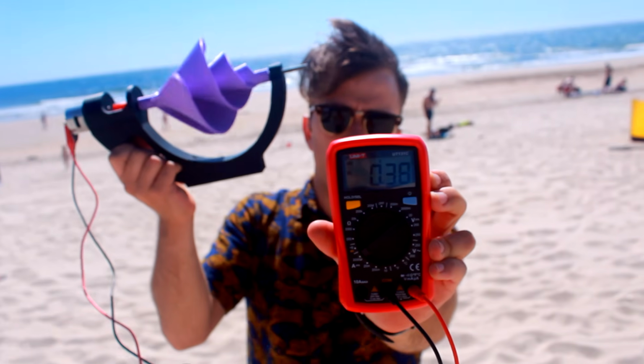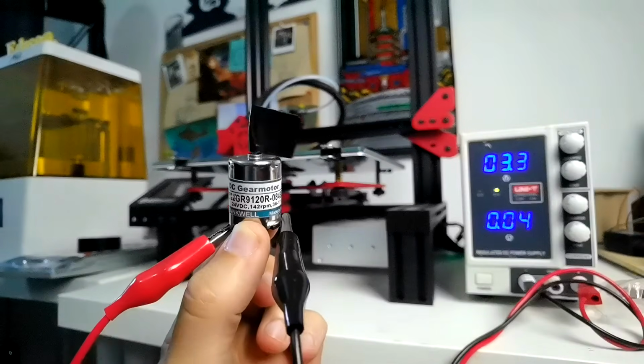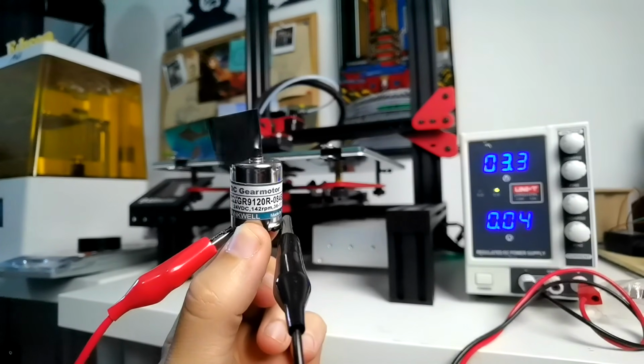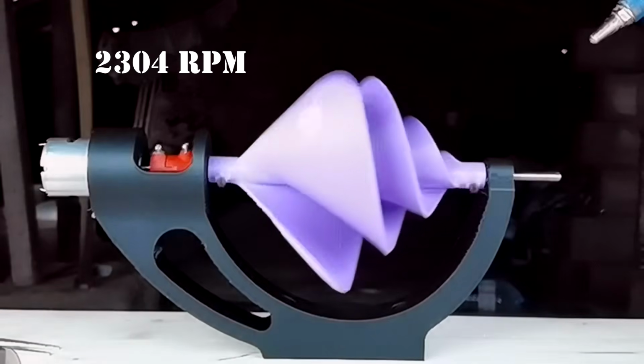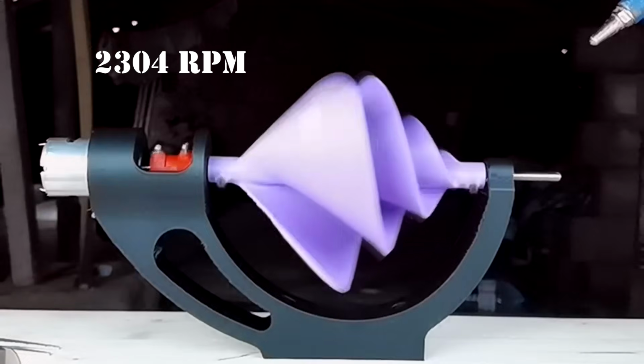The reason I could barely get to 1 volt was because I was using a high-speed motor as a generator. This type of motor gets to almost 20,000 RPM using just 3 volts, which also means that to use it as a generator and get 3 volts, it needs to spin at almost 20,000 RPM. And even with my compressor, I was only getting an output speed of about 2300 RPM. Using that motor was a bad idea, but most DC motors behave like this.